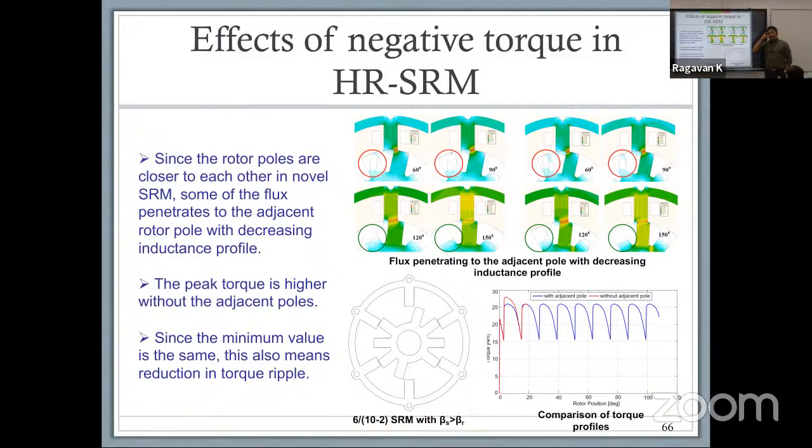One question that actually came up as we have published in the journal was they were saying that when you increase the number of teeth on the rotor, you might end up with a negative torque because there is still a tooth that is in close proximity to the stator. So in order to verify what that does, we actually eliminated in the design, we took out one of the teeth, on both sides. And we applied current to see what the difference in our torque reduction was.